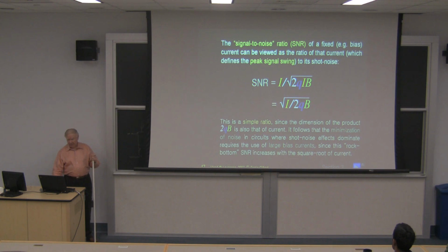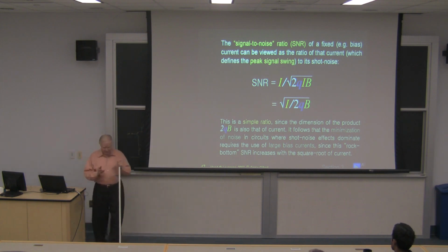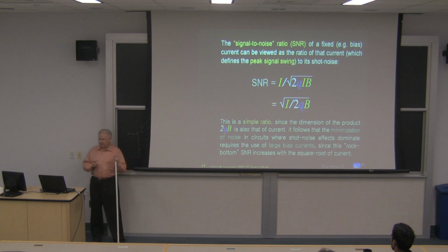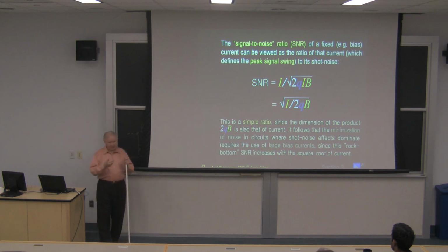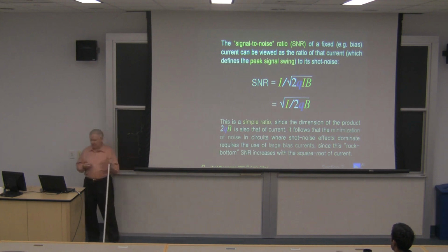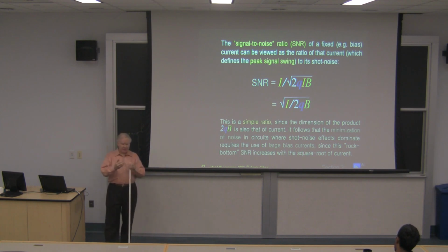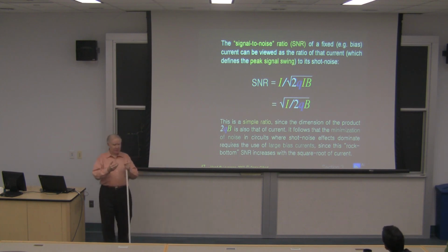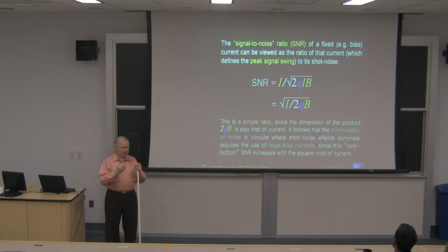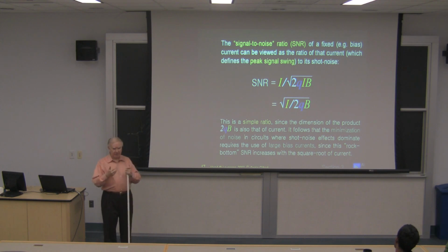Okay. Now, here's a thought. You may ask, well, what's the dynamic range of a current? Now, again, an ideal current would have infinite dynamic range if it doesn't have noise. But to the extent that it's going to operate on a junction device, shot noise becomes one of the most important noise generators. You ask, does a current really imply a certain dynamic range? In other words, can we get 110 dBs of dynamic range at a 1 picoamp current in a junction